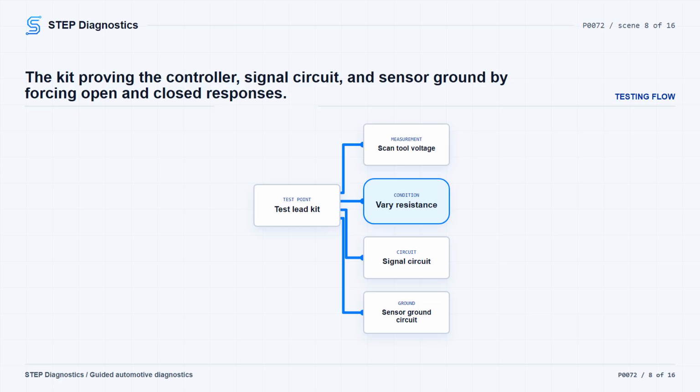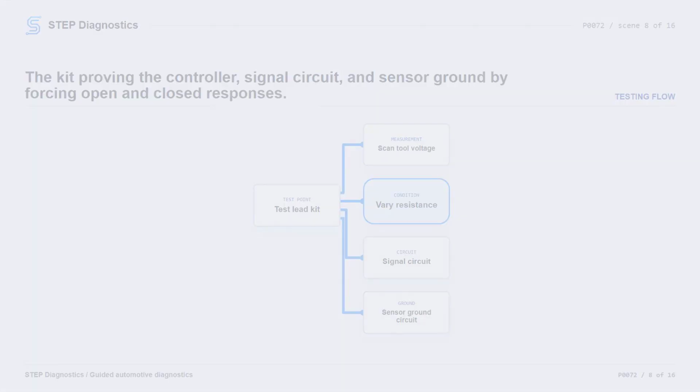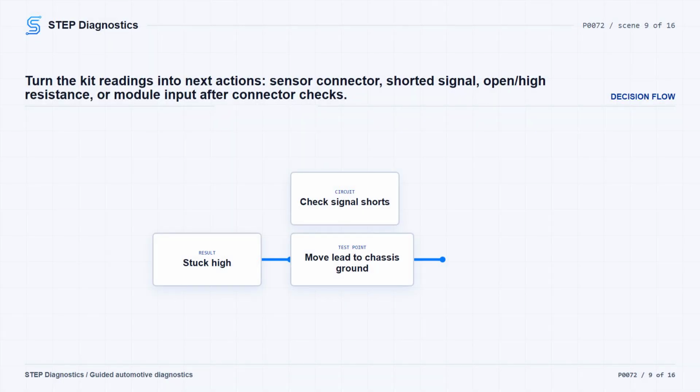If the signal is stuck low or only the circuit low fault sets, focus on the temp sensor signal circuit shorted to chassis ground or shorted to the sensor ground circuit. If that signal circuit is not shorted, inspect the related connectors for terminal problems before condemning the ECU.